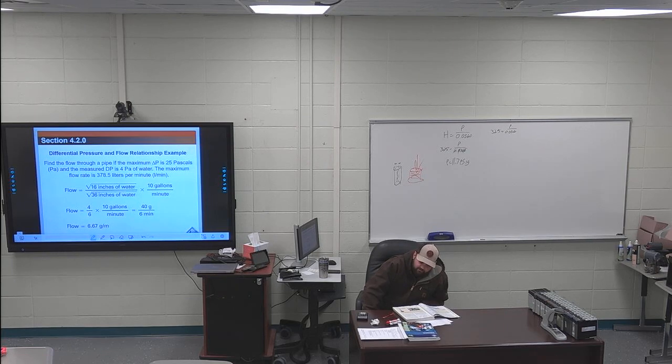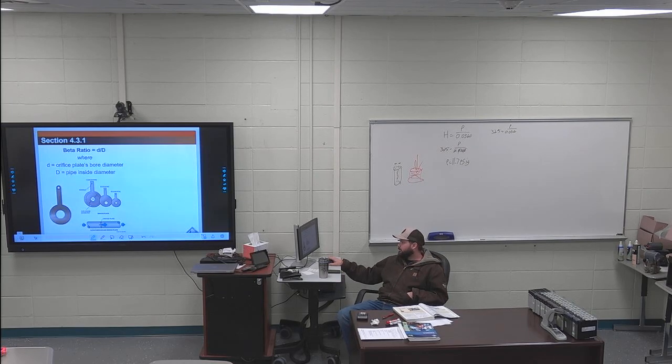Page 35, 430, differential pressure flow measuring devices, orifice plates. Everybody remember me talking about orifice plates last time? For you guys that have done P-Tech, you should know what an orifice plate is. It should work the same way as making the pipe smaller, to raise the velocity. That's what this does. So these are different ways of making the pipe smaller.